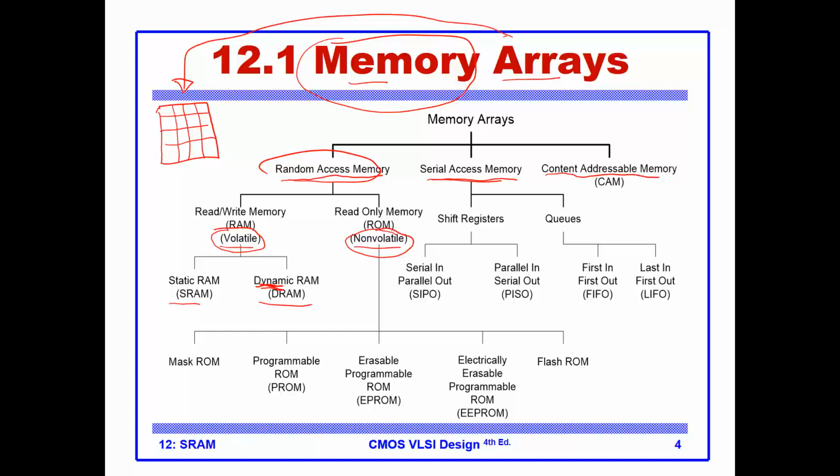It stores the data on a capacitor. And we all know in these environments of small electronics that there is this leakage current, and so these capacitances leak the data. So we need to refresh the data frequently and periodically in this type of dynamic.